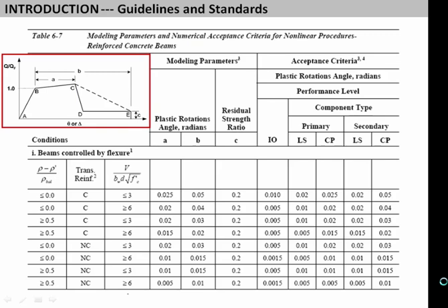But to me, the big improvement that came with FEMA 273 and ASCE 41 now is that it provides tables like these with modeling criteria for different kinds of structural components, in this case relating the deformation capacities and so forth, the reinforced concrete to tie spacing. And this is, I think, as a practitioner, what really lets you do nonlinear analysis and doesn't make it a research project each time to come up with your nonlinear analysis model. So I think we're building on ASCE 41.